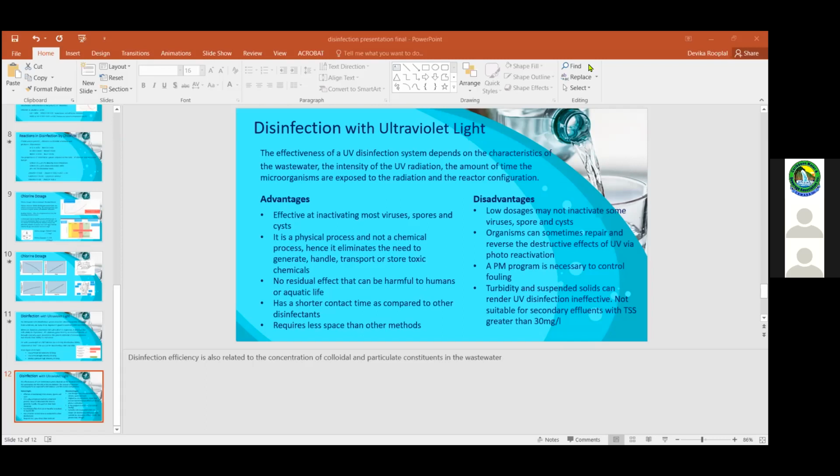your distribution system needs to maintain a residual of 0.5 milligrams per liter or 0.3 milligrams per liter. Now, there's no way to firmly tell you how much chlorine to dose, because it's a dynamic, continuous process in that your wastewater or your water concentration is never going to remain constant. You have a range: this is what my organic content is, this is what my pH is.